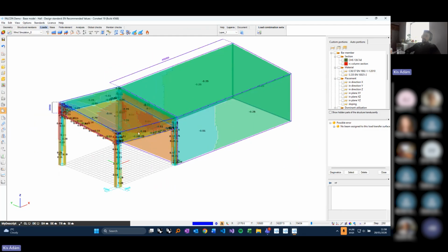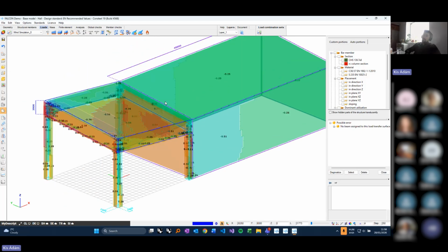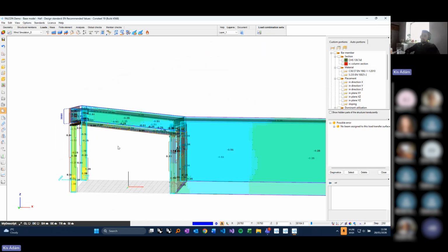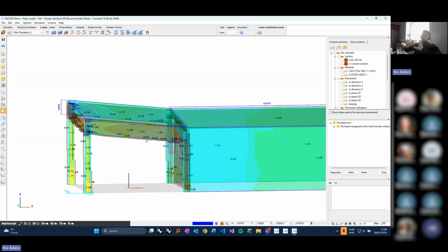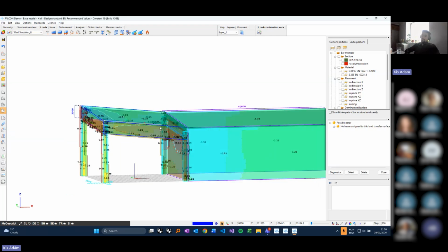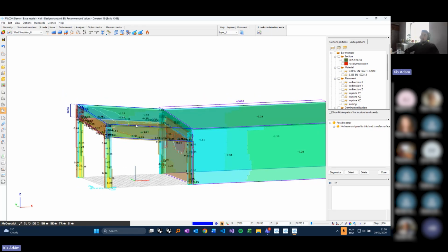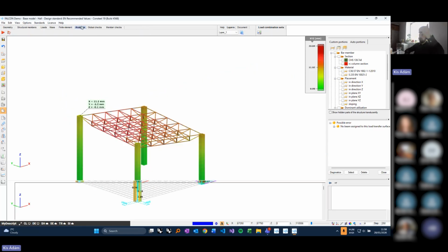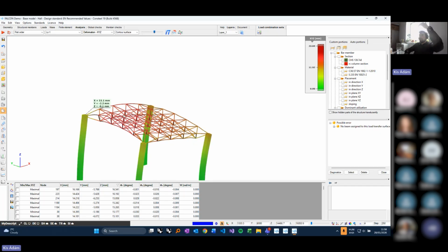Because there will be certain vortices being created, and because there will be a certain pressure close to this, it affects also the roof at a certain level, and the actual uplifting of the roof structure will be a bit higher. This is why when we actually are using these results of our simulation result, the actual load case for calculation,